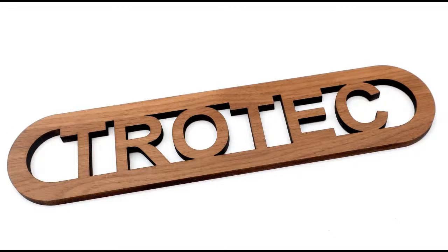This would work just as well if you put a block along the bottom and you wanted the letters just to stand on their own. In that case, I would take the letters and just draw a box, and then you can just use the weld button and weld them to it. In this case, I need to use front minus back because I wanted the inside to stay and not just weld together. So there's a lot of different tools up at the top for allowing you to trim: front minus back, back minus front, the weld commands, and to create different scenarios and offsets depending on how you want the graphic to be welded together. In this case, I needed the inside, which is front minus back.